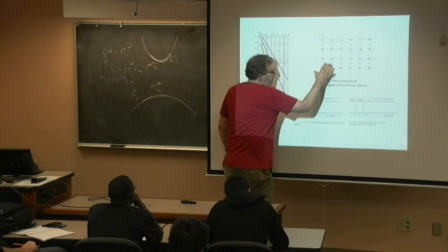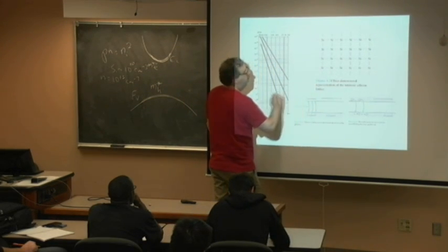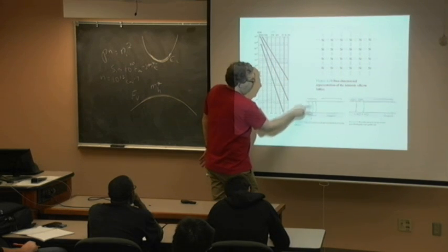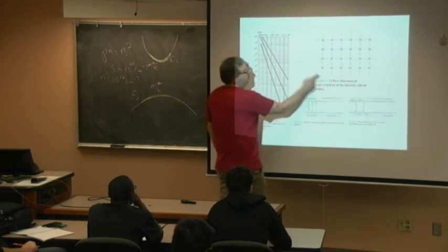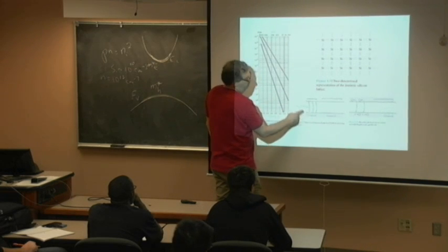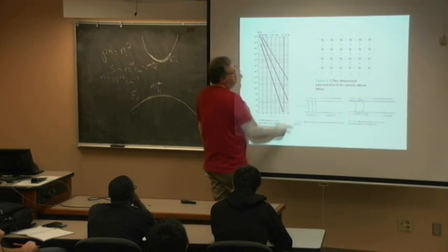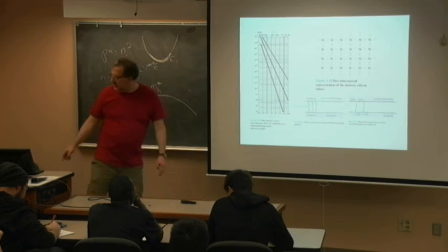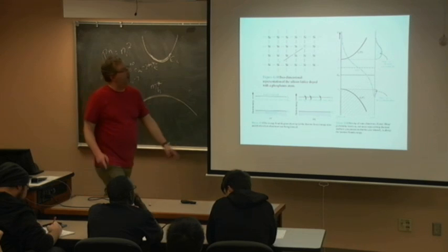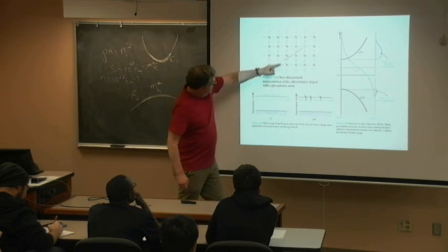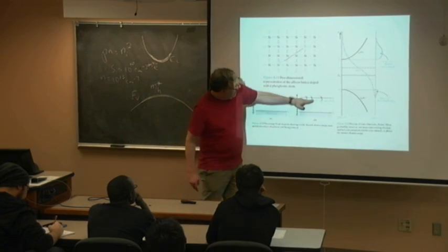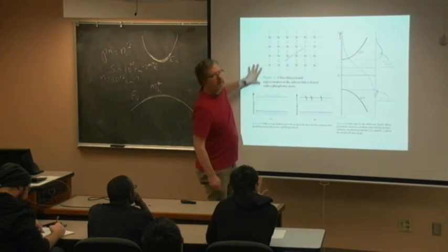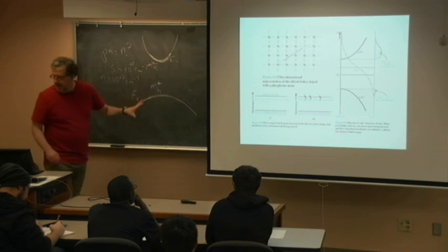It shows the crystal, kind of brings you back to the crystallography. Here's the silicon. I have no impurities, so the only electron-hole pairs are the ones that are ionizing across the gap. I'm breaking a bond, and those are ionizing, and so therefore I get the intrinsic carrier concentration. Or I can put in a phosphorus, creating that donor level, which ionizes, which skews this up. These are nice diagrams because they really tie it all together.